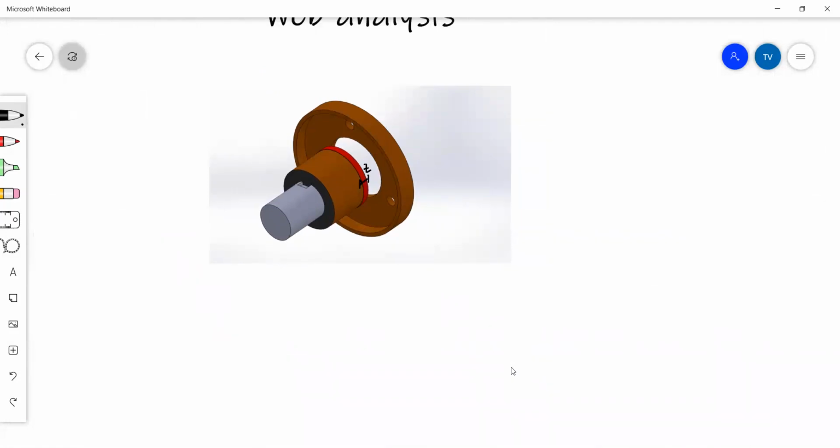All right. So can anybody tell me what type of forces will we be experiencing on the web? It's always useful to first define what type of forces you'll be working with. So this hub is turning with some kind of torque, and it's creating what kind of force on this red surface? If you look at it, the force would be acting like this. And you can see that it's on the surface and not perpendicular or not shooting out of the surface. So it's a shear force.